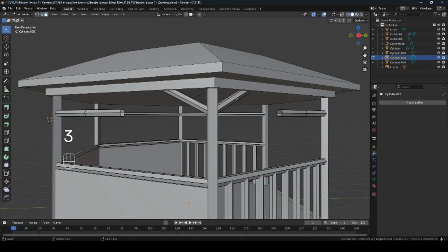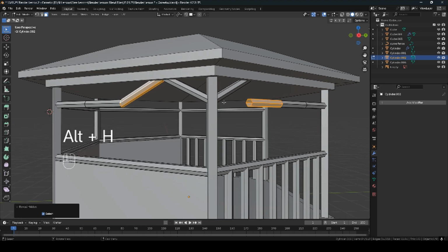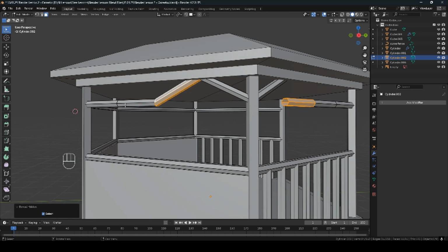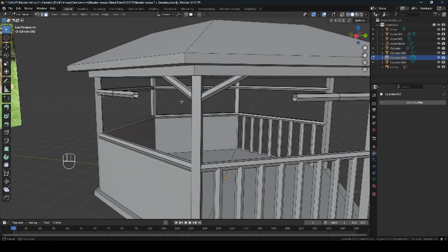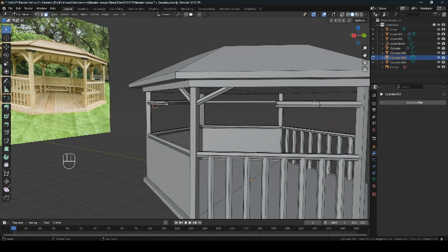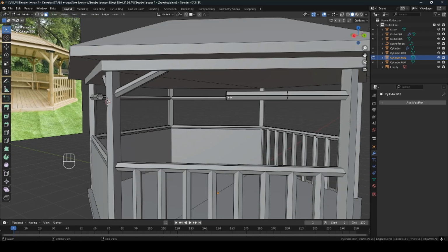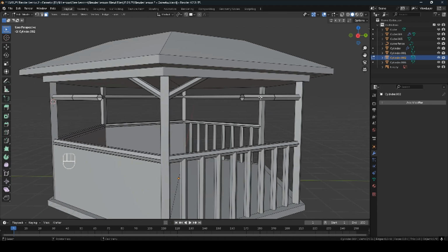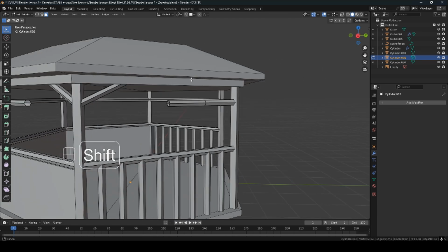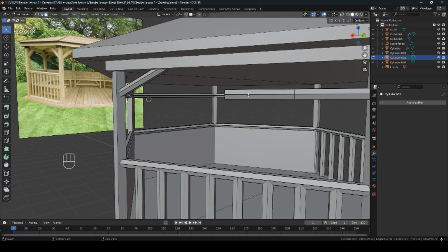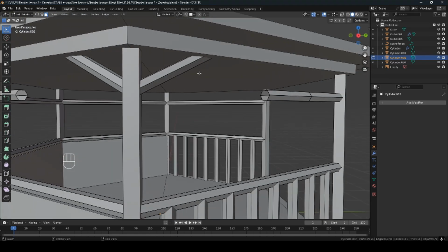We want to now press Alt H, so it's going to bring back our mesh. I didn't press V this time to unlink that because I realized, well, actually we can just delete these, so that won't make any difference at all. Sometimes you might want to press V to unlink the attach and detach it. Say for example, if you press V to detach, this is a good idea when you can also select all and press M to merge the vertices together, which I did cover in my first lesson. So feel free and look for merging verts together so you can connect meshes together as well.